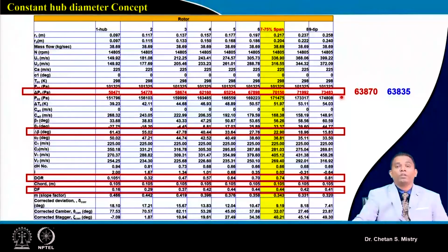Now, we do not have any configuration saying what the tip clearance will be. Suppose this is known to you, then accordingly you need to adjust your delta P0. If you recall, when we were discussing the subsonic compressor design, we configured it considering tip clearance to be 3% or 2%. Accordingly you adjust your delta P0 such that the pressure drop or loss happening near the tip region gets compensated.